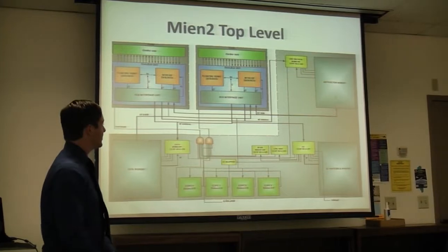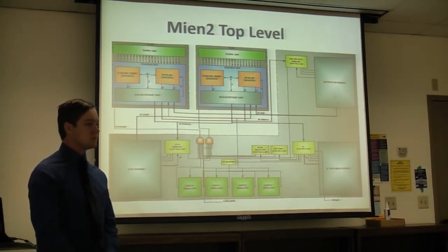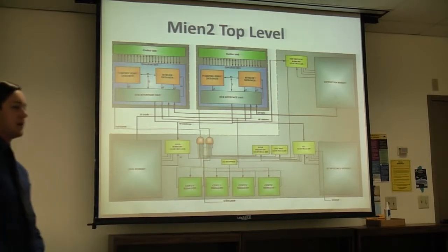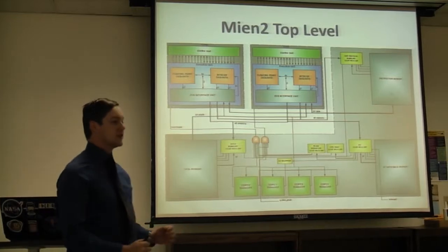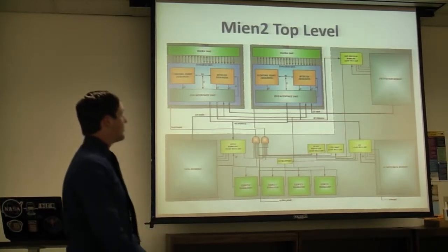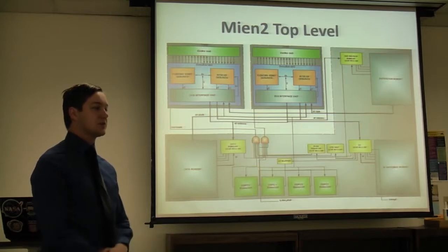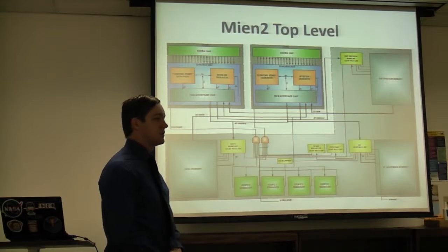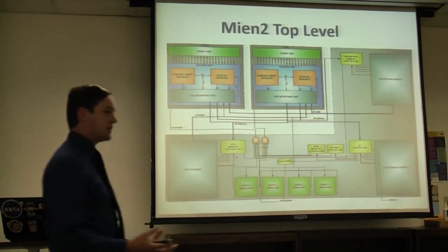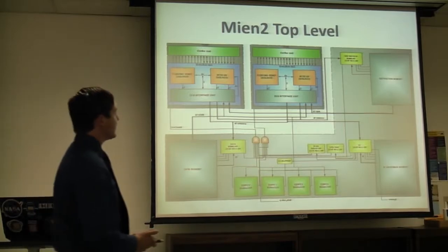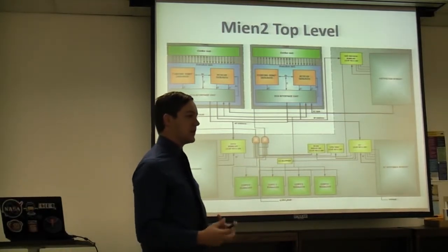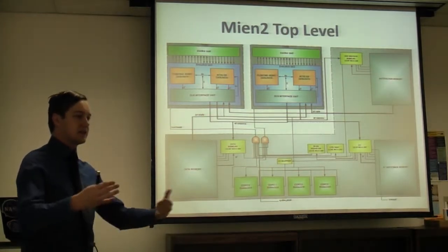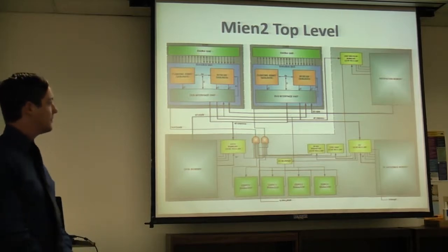All right, so you guys talked about interrupts. I was wondering, because you have multiple cores, how they handle a single interrupt. They can both implement interrupts. So they both actually get the same interrupt signal, and they can implement interrupts in a completely different way. So do they have separate interrupt enables? Yeah, they're set separately. So one core could be enabled and the other could not. They run the same ISR. You can set a register inside the core to let it know which core it is, which ISR to run. But this allows both of them to get the data from the interrupt, if need be.